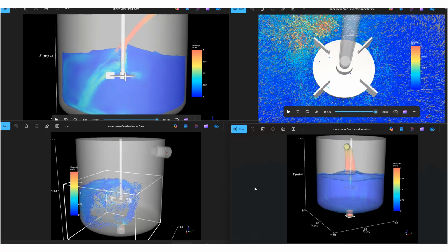When you do your calculations, the default mode is to do the Eulerian calculation, so it's a continuous profile, and you can use it to see through your domain as well. Basically, it allows you to have a transparent fluid zone, and you can see the profile that should match closely what you have in the particle SPH view as well.